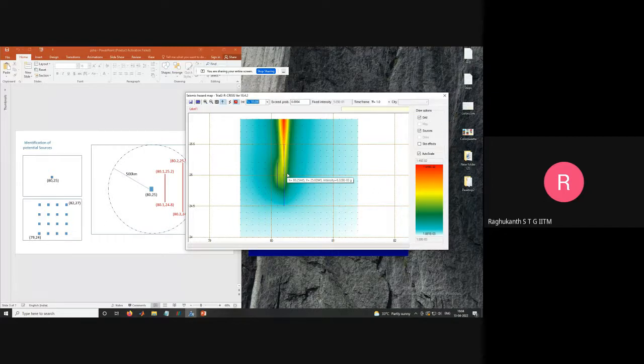For example, if it is 8.5 magnitude, generally what happens is long periods, like 10 seconds or so, will be excited by higher magnitudes. Small magnitudes will not be able to excite this high natural time period. So you can change it to 8, what happens? You change it to 5, what happens? You can try those things.